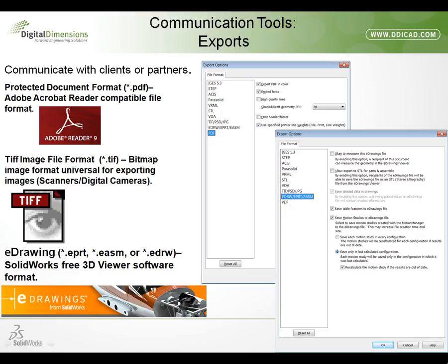When you zoom in really tight, you'll be able to see the individual color squares that, when combined together, make up your image. Vector images, on the other hand, is coordinate data. SOLIDWORKS produces vector graphics, and so long as your PDF is black and white, it will output vector graphics.